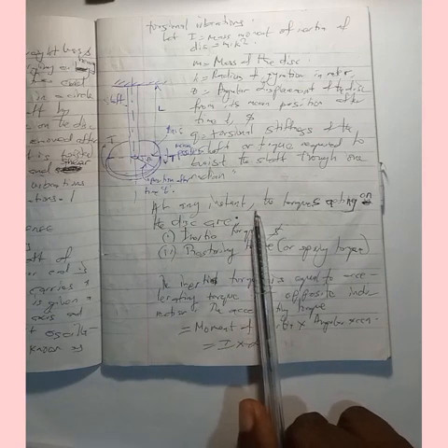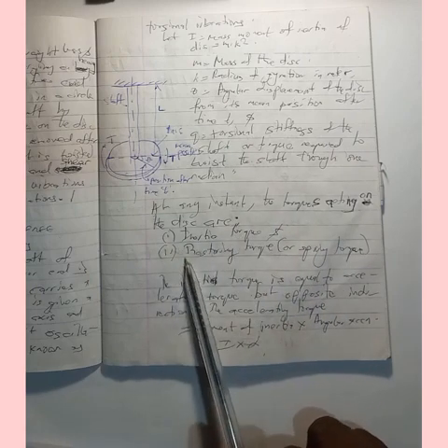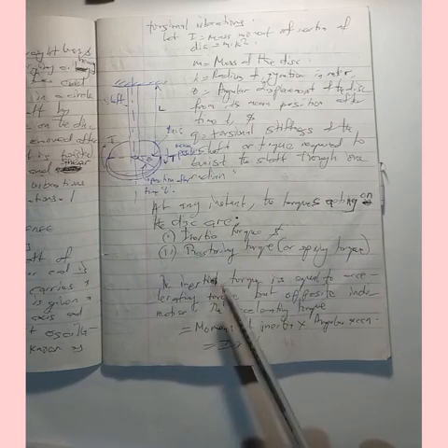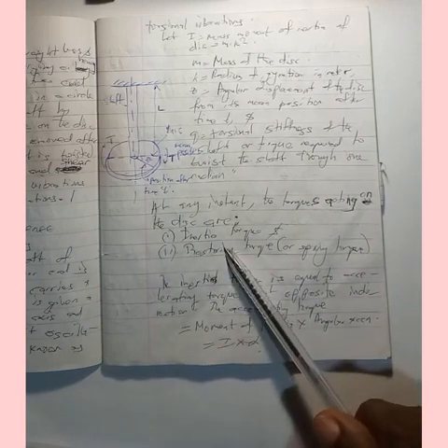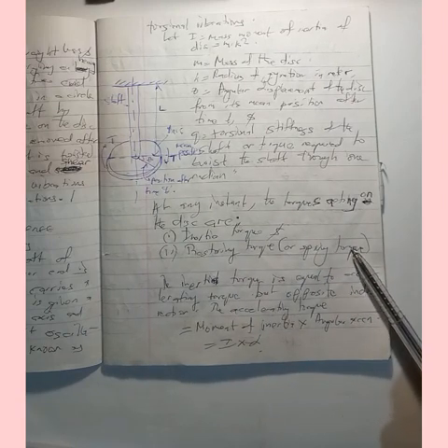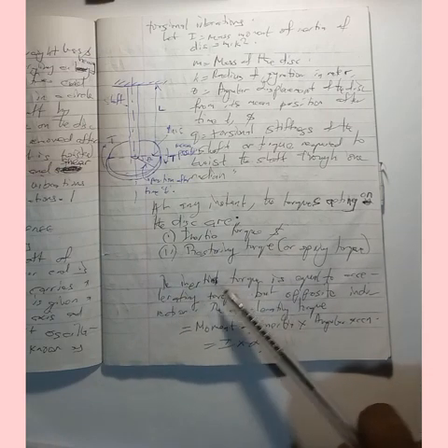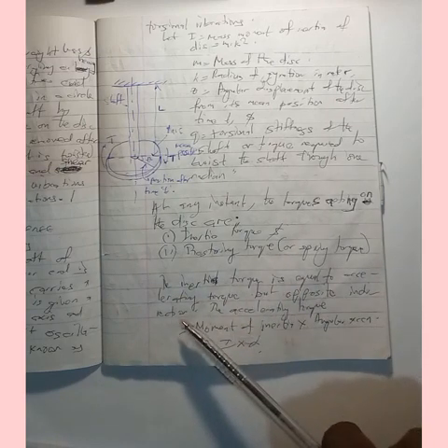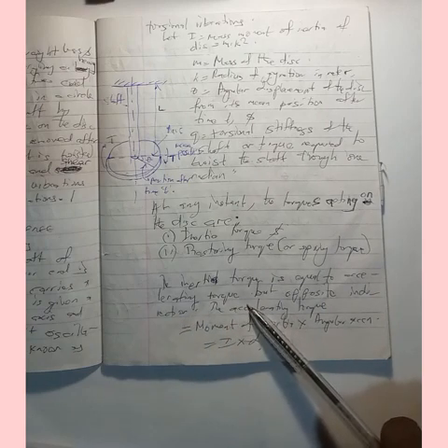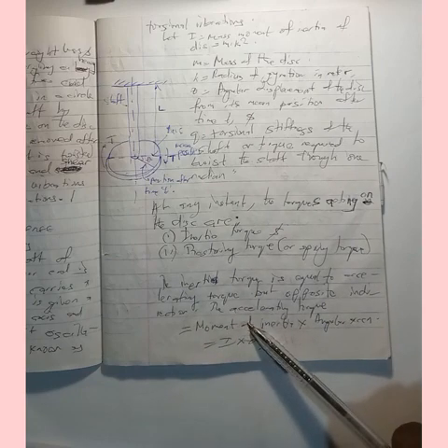At any instant, we have two torques acting on the disc. The first torque is the inertia torque, while the second torque is the restoring torque or the spring torque. The inertia torque is equal to the accelerating torque, but it is opposite in direction.